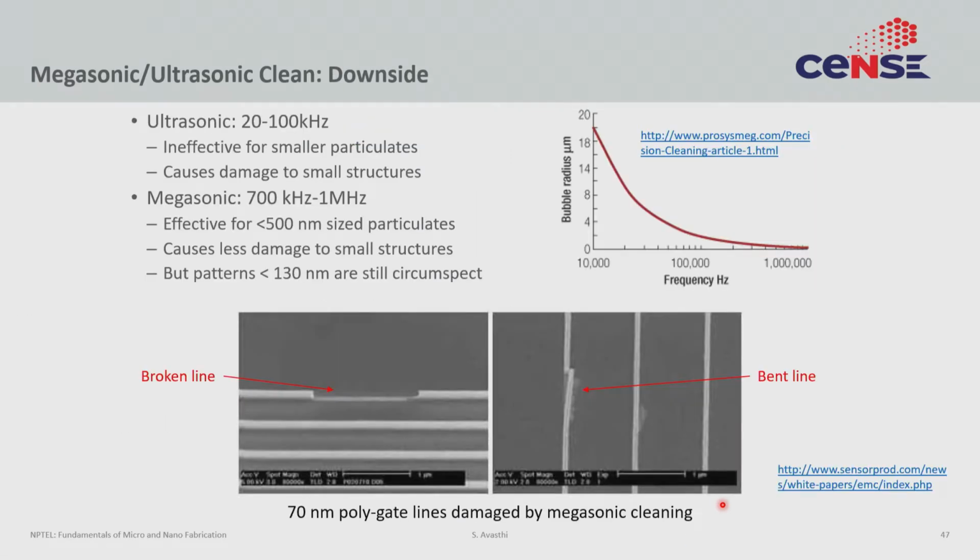However, nothing comes for free. This mechanical energy can cause some damage on the surface, especially if you have very small features. Whether the damage will happen or not depends upon A, how small the features are, and B, what frequency you are actually using to do the cleaning.